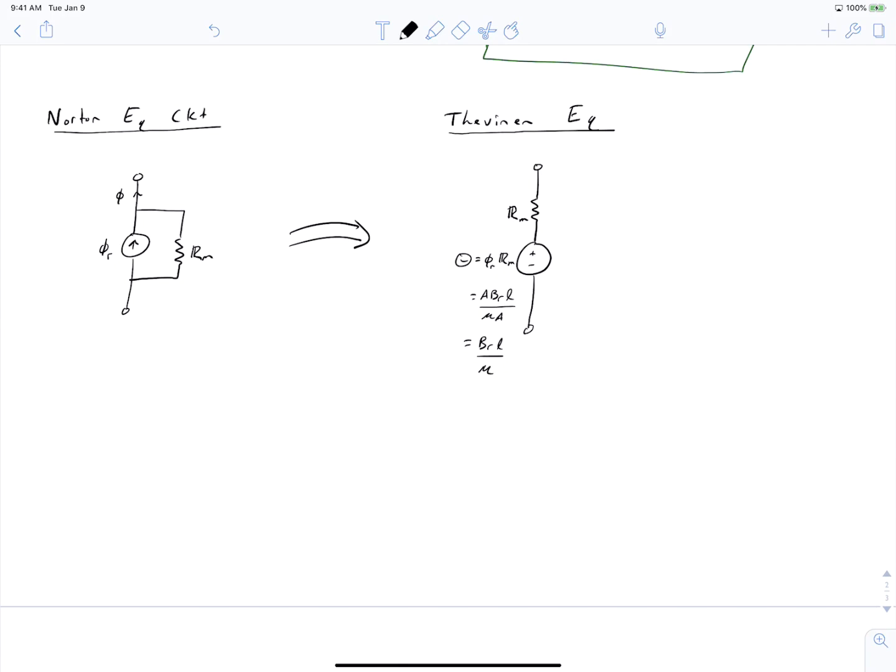So if you've got a magnet that you're using to magnetize your circuit, and you want to increase your field in your magnetic circuit, this shows that you have a few options. You can pick a magnet with a larger remnant flux density, but if that's not an option, you can increase the length of the magnet, you can increase the height of the magnet. And that makes more sense. You've added more magnetic material that is now able to push flux along this path.